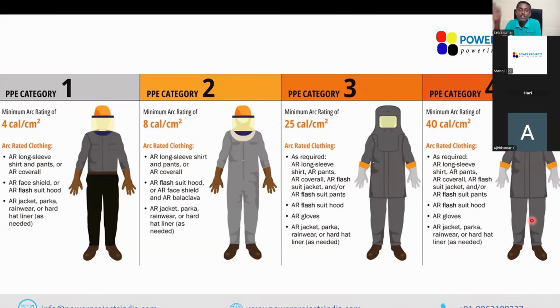That's almost impossible. I would always strongly suggest you to limit personal protective equipment and the incident energy, and hence, of course, to less than 25 calories per centimeter square. There are companies who limit the incident energy to 12 calories per centimeter square also. So there are multiple methods to limit the incident energy.